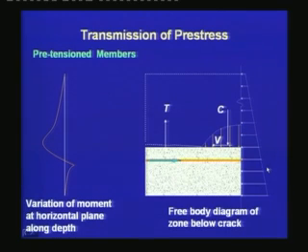The prestress, which has been transferred beyond the transmission length, and the prestressing in the tendon, is under a self equilibrium, and there is a moment acting in the horizontal plane whose variation is shown in this graph. That means as we go along the depth, the moment is such that it creates tension on the left hand side,